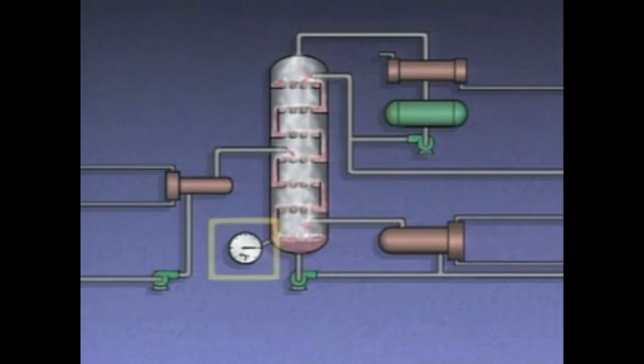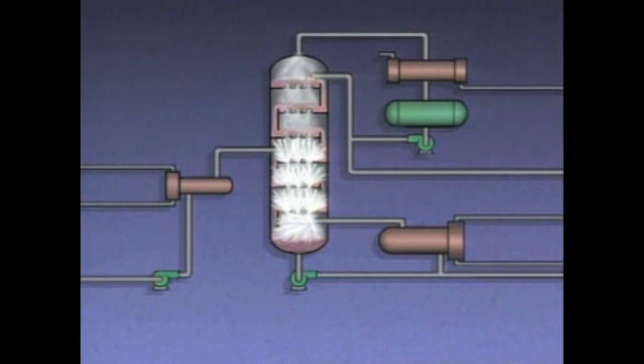Excessive liquid flow down a column can cause overloading and flooding, but trays can also become overloaded because of excessive vapor flow up the column. One of the most common causes of excessive vapor flow is too high a temperature in the bottom of the column. If the temperature in the bottom of the column is too high, too much liquid is vaporized, and the vapor flow rate up the column increases. The increased vapor flow forces liquid up the column, flooding trays in an upward progression.